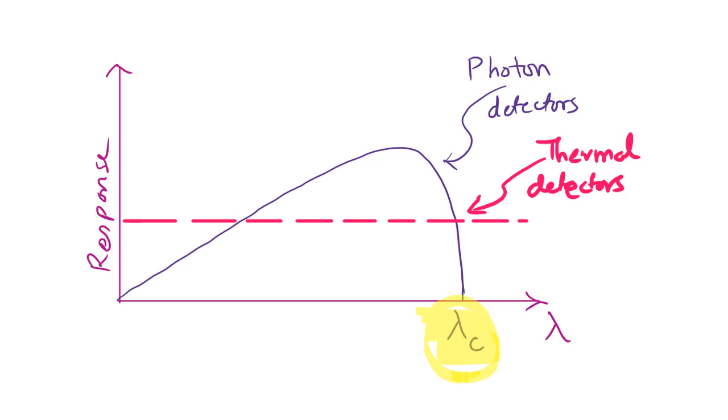In contrast, you have the thermal detectors, which, as I said, largely rely on notions of black body radiation, where there is a broad absorption of radiation across wavelengths, because the energy absorbed eventually turns into a change in the temperature, and that temperature change is what is being recorded or measured. So these detectors are largely broadband and are not limited like the photon detectors in terms of wavelength.